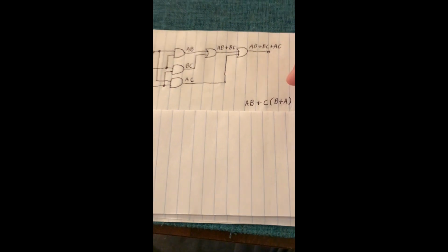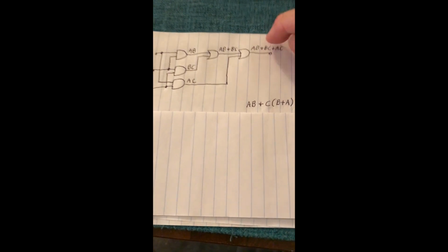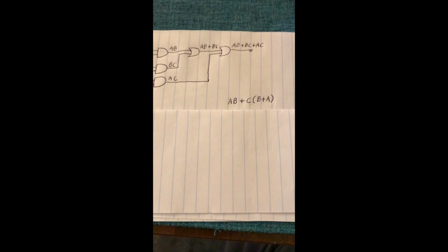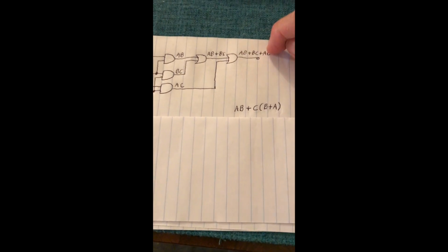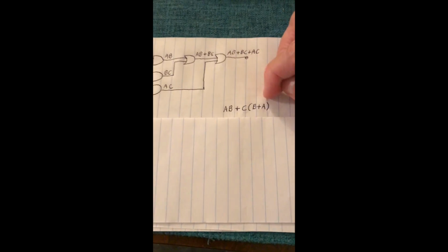And yes, if we take this expression, rewrite it down here, and then factor it, well, we can factor it in multiple ways, but I'm just factoring it by factoring the C out here from these 2 AND statements. And yes, that's the distributive property of AND over OR, just like the distributive property of multiplication over addition in arithmetic. That's something that you can prove to yourself using truth tables. You get exactly the same truth table result from this as you do from this.